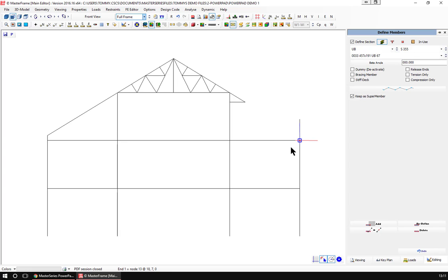It's very, very simple. Any member can be created, and if I just look at what's happening here, I've got a mid-span. I can go along, in my case, I think it's at 0.25 of a meter, and this one is the third points. I can come out and I can say give me to the mid. I can also say give me to the third or to the perpendicular, which is very, very useful. Or I can hover over this one, for example. Hover over this member, and I should be able to get parallel to it if I really want to, and I'm coming in with that parallel just there. So that's the parallel to it.